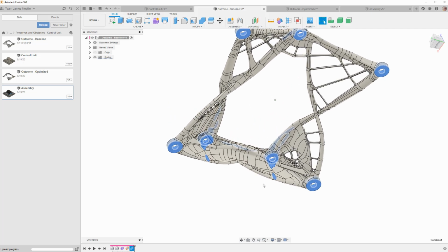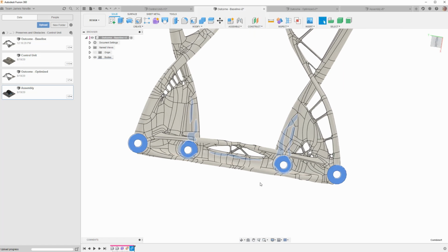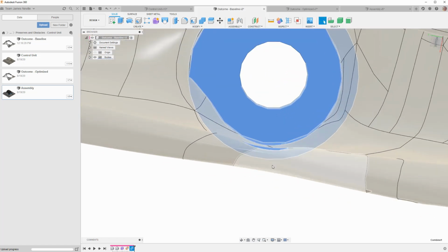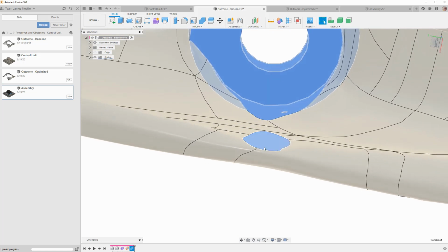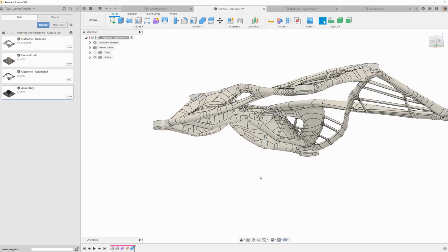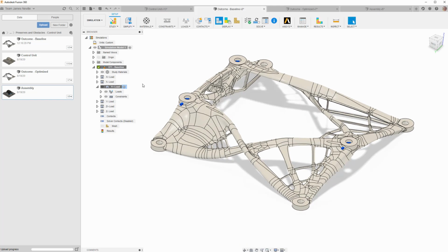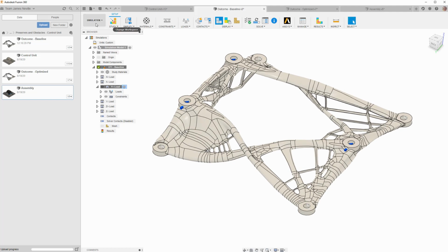But I see an egregious gouge here, actually two of them. The access obstacles, for tool access to reach the bottom of this preserve, you can see it actually gouged out a pretty good chunk right there. That reduced maybe 15 or 20% of the thickness of this particular member, this portion of the generative study. So let's take a look at the stress analysis and see the impact of these assembly cuts. So here I am in the simulation environment.